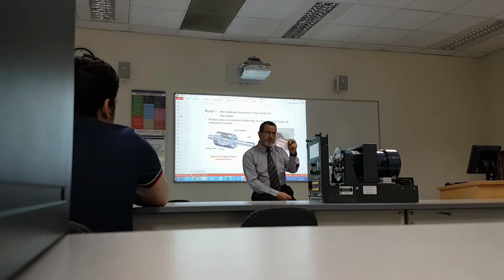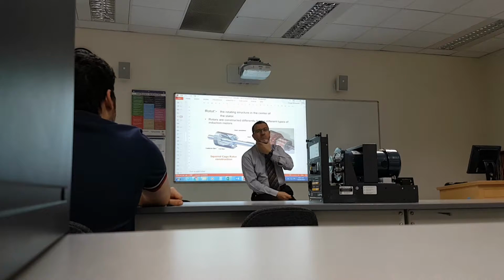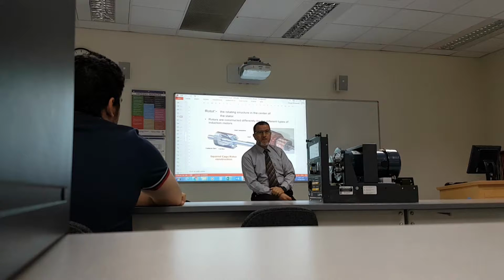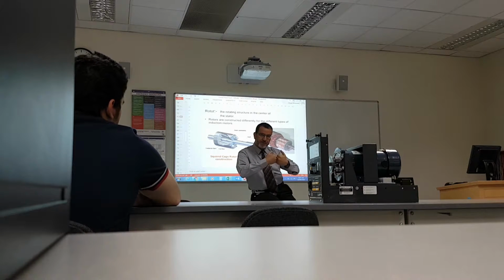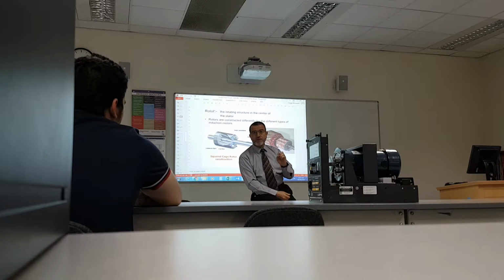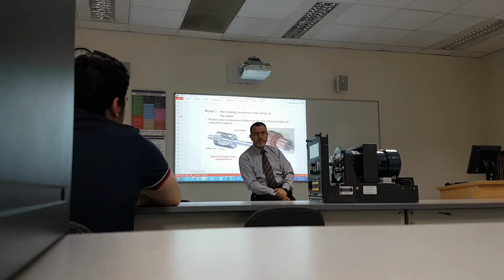Pull-in means the torque that is needed so the motor could reach synchronous speed. It's being pulled into synchronism by the action of magnetic attraction. That's why in synchronous motors you never turn the excitation on until you're at least 90% of synchronous speed.